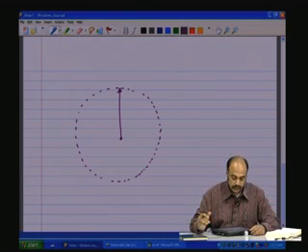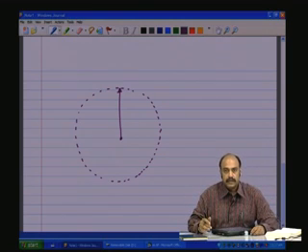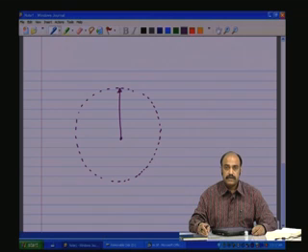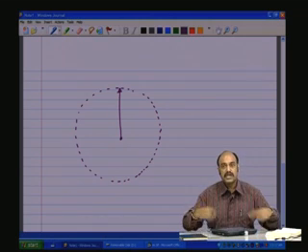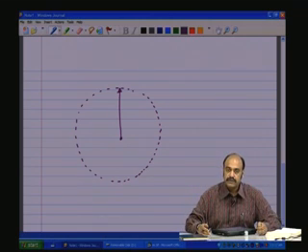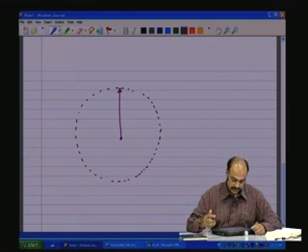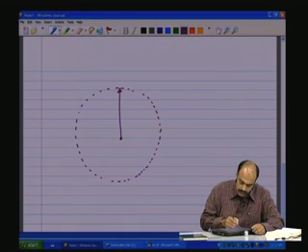If we apply 120 degrees electrical phase shifted sine waves to the three coils, which are also 120 degrees phase shifted in the mechanical, that is in the stationary spatial coordinates.